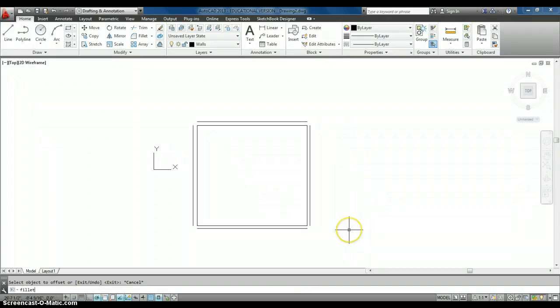And then finally, I'm going to close the corners of my walls using the fillet tool with a radius of 0. So I just select my two lines. If you create one fillet, it's going to automatically close out after you complete that fillet. If you want to do multiple fillets, after you've selected the fillet and changed your radius to 0, you can type M for multiple. In that case, you can just select all your corners and your fillet will not close out.